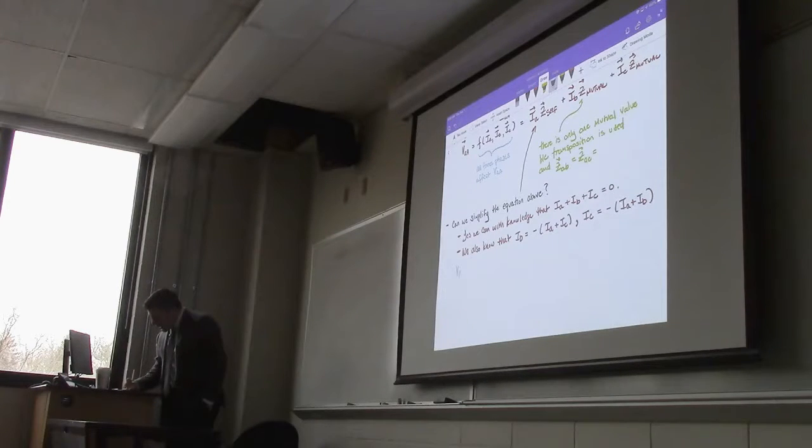We know that VAA is equal to IA Z self plus, now I'm going to substitute in for IB. I'm going to say this is equal to minus (IA plus IC) times Z mutual.